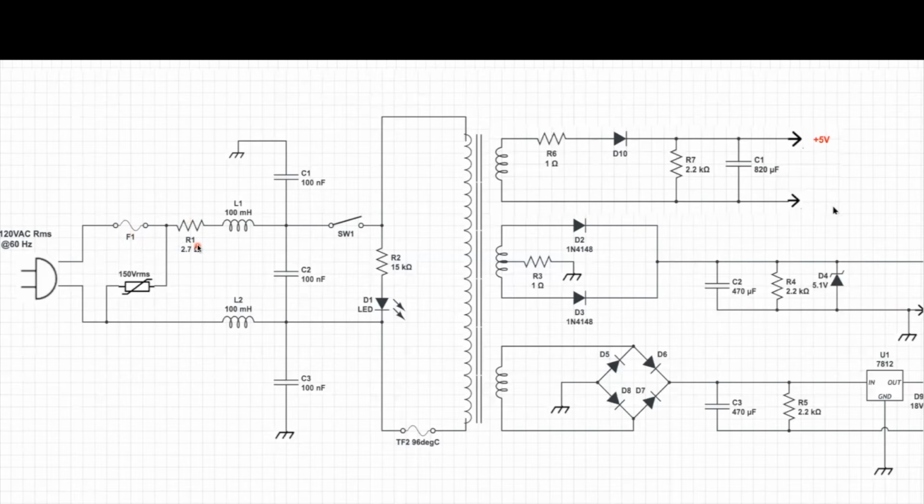Now, he said something that actually happens. Somebody put the wrong value fuse in. It's a 1 amp fuse, and they throw a 10 amp in there. Well, the engineers put a 1 amp fuse in there for a reason.